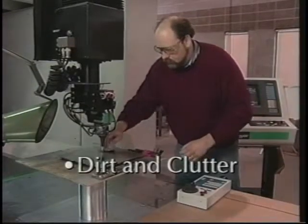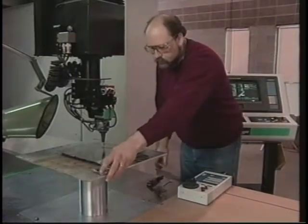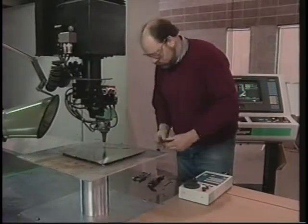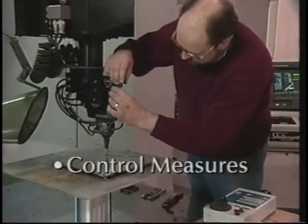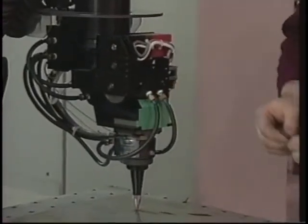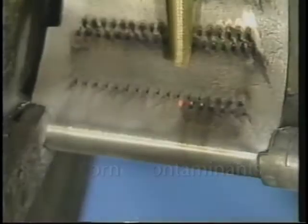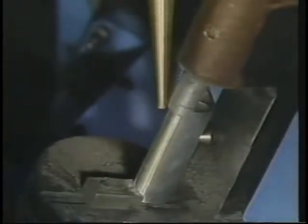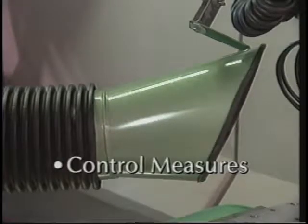Manufacturing is often a harsh environment for laser equipment. Work areas are sometimes dirty and cluttered. Dirt from cutting oils can infiltrate a laser system and cause the equipment to malfunction. Make sure the work area is clutter-free. To ensure that lasers are clean and operating properly, perform routine maintenance. When high-powered lasers are used to cut, drill, or weld metals, plastics, or composites, potentially hazardous airborne contaminants are generated. Evacuate airborne contaminants with an exhaust ventilation system.